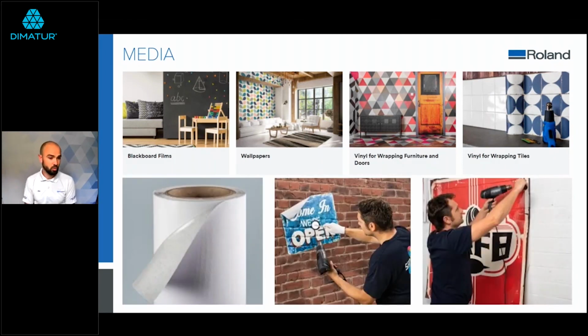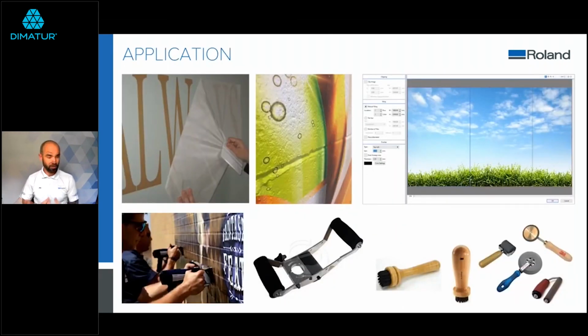And again, just a few more pictures there of some of the different solutions. So those textured wall films, which are great for that interior decor look, rather than having a glossy vinyl, which might detract from, or attract too much light, or maybe look a bit too shiny, or maybe need a bit too much cleaning. You can use those textured films, which would mimic normal wallpaper films as well. And then those types of vinyls where you need to use a heat gun to go into the recesses and things. In terms of application, we've mentioned application tape.